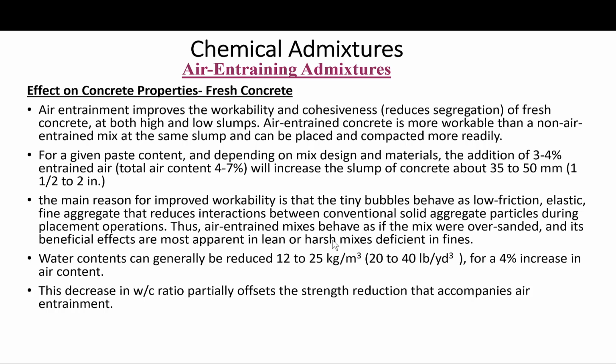Although, as we said, air entrainment admixtures are added primarily to improve the durability of concrete, they have other important influences on the behavior of both fresh and hardened concrete. For the fresh concrete, for example, air entrainment improves the workability and cohesiveness of the fresh concrete at both high and low slumps generally.